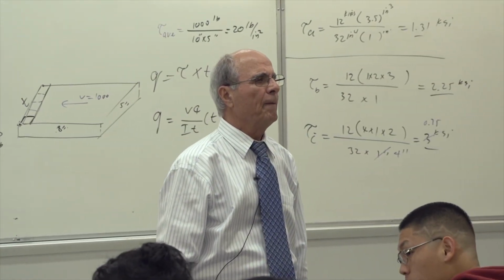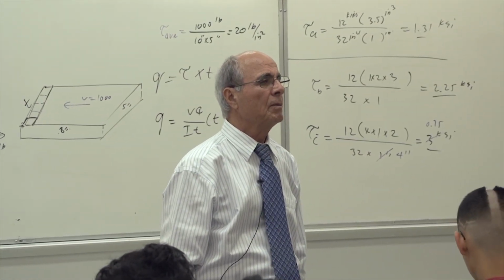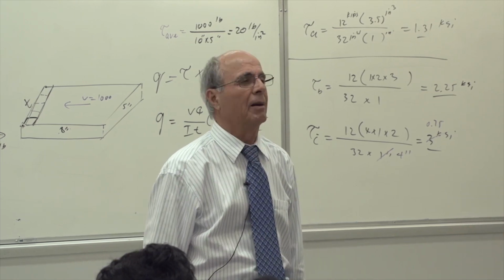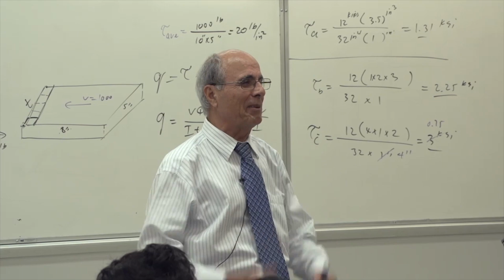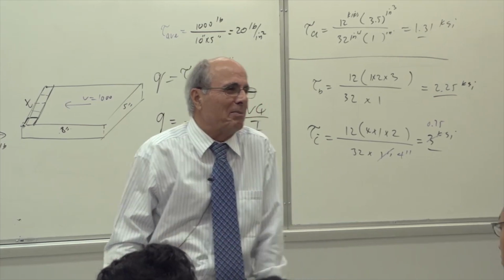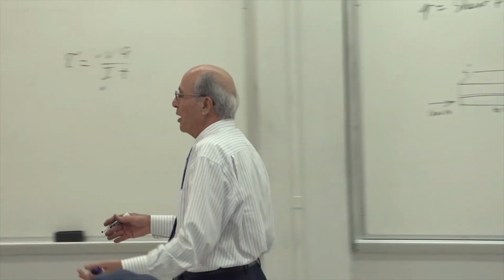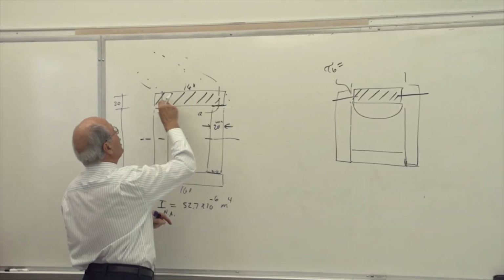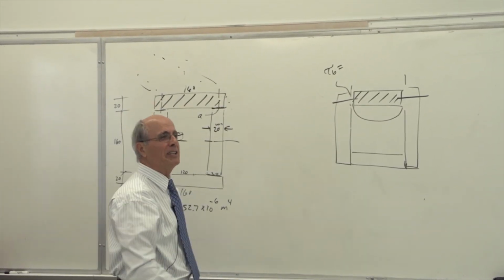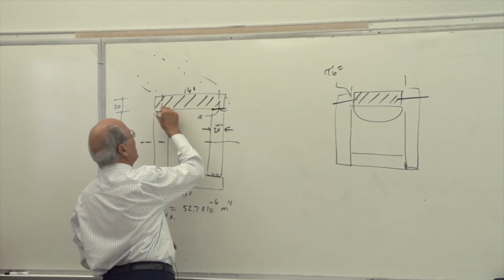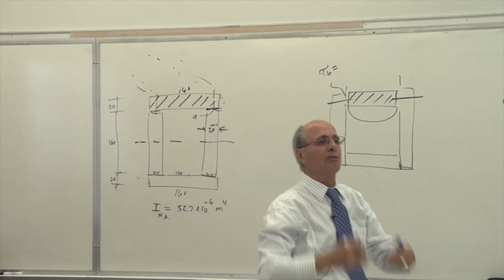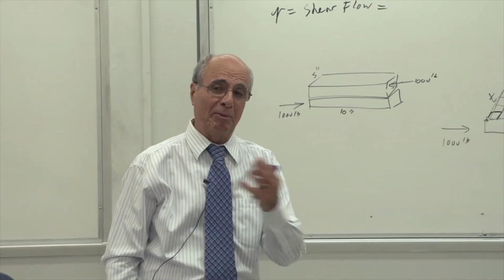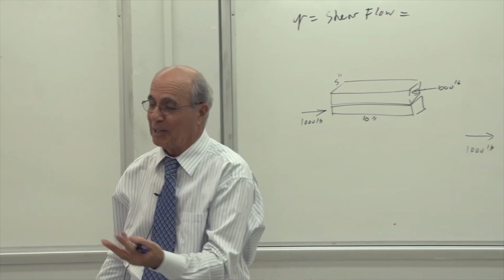What value of Q did we use for the nails? The Q of where we cut the nail, right? Yeah, the nail will be at that level. The rest of it doesn't matter. That's the whole idea. I hope you understand that part. The nail doesn't shear off there. The nail shears off here. Is that correct or not? That defined your Q. Everybody? Because that's the very basics.